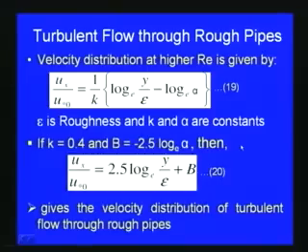For smooth pipe, to find the velocity variation, we have basically used the power law and the logarithmic law, and then we made some comparison with the Nikuradse measured experiments and the corresponding expression which Nikuradse has derived, and it is coming very nearby. So, we can rely upon these kinds of expressions for velocity for turbulent flow through smooth pipes.